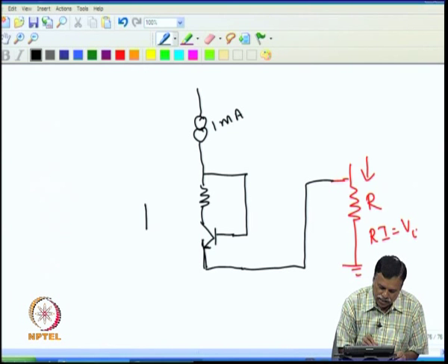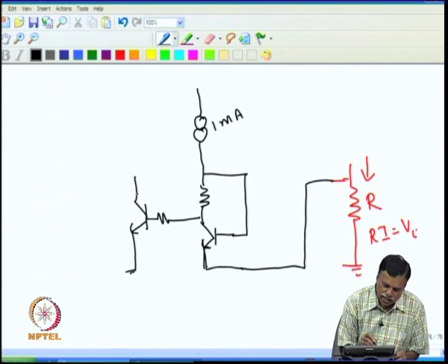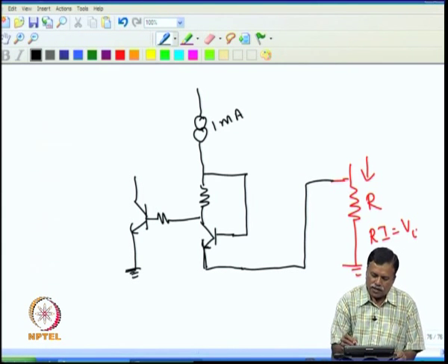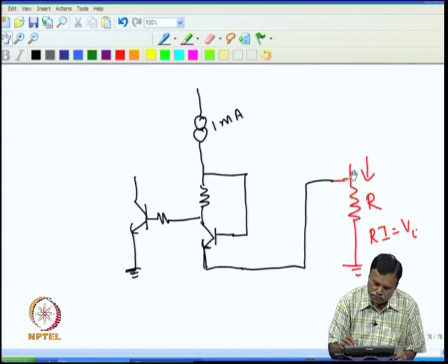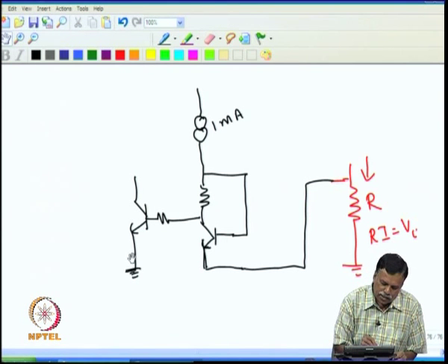Then assume that another transistor, this is the transistor which is to be switched off. So, I connect this here. Now, this may be a relay, or it can be any other load. So, it is immaterial. All that we want is, if the current flowing through this is more than a particular amount, we want to switch on this transistor, that is our aim.